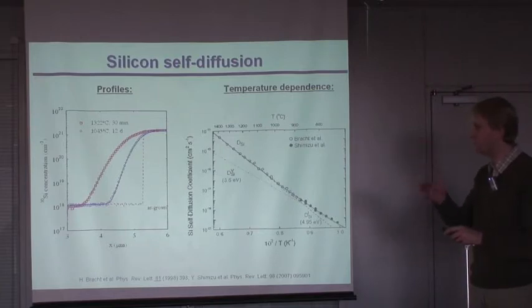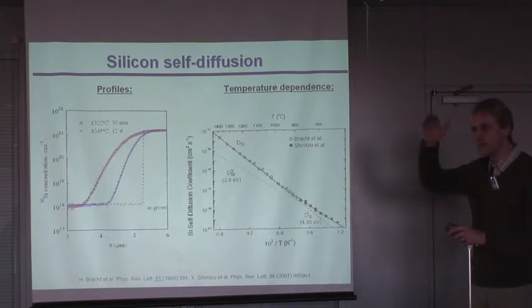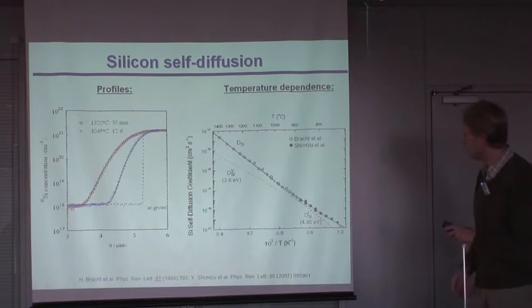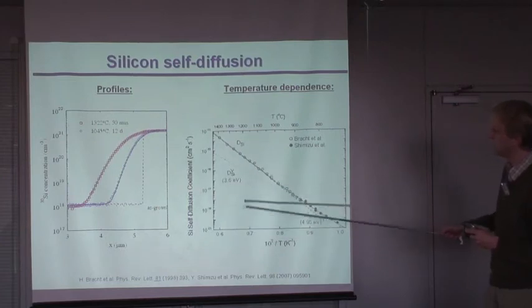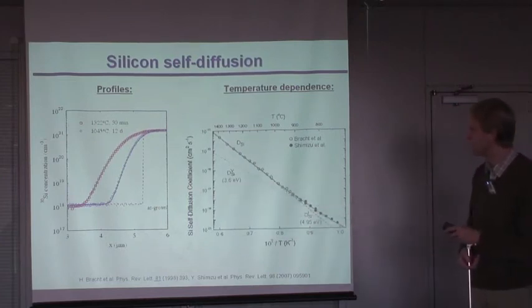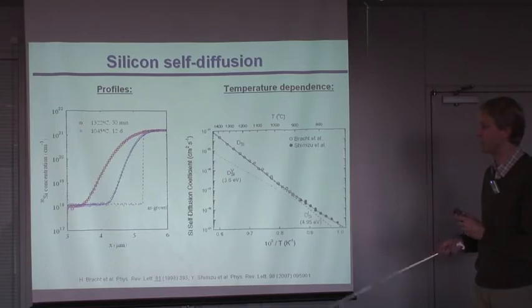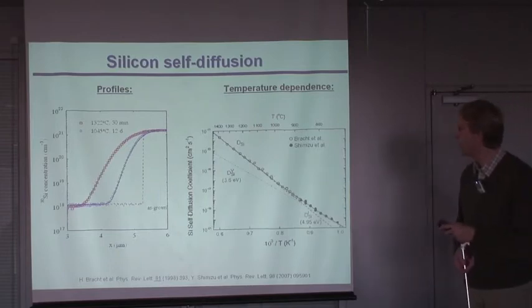So due to the periodicity of your isotope structure, you have a certain Raman signal, and if now an intermixing takes place, the Raman signal decreases, and this you can use in order to determine the diffusion coefficient. And this has been then extended in that range here, and based on these results, you have determined the vacancy contribution to self-diffusion with an activation enthalpy of 3.6 eV.